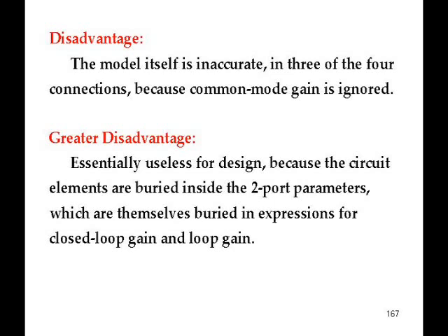There's only one of the 4 models which is correct, the only one that doesn't require common mode gain, which is the parallel-parallel connection. So the disadvantage of this method is the model itself is inaccurate for 3 out of the 4 connections because you ignore common mode gain. But whatever, the real disadvantage is much worse than that. This is essentially totally useless for design.